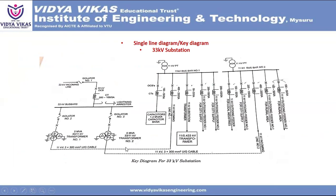From transformer 1 and transformer 2, they give another bus bar, number 1, the 11 kV bus bar. This is the 33 kV bus bar. This is the 11 kV bus bar. And then from the 11 kV bus bar, they give a capacitor bank to improve the power factor. And then this is the incoming circuit. And then from the 11 kV bus bar, they give an auxiliary transformer for the substation power supply. And then they use an 11 kV potential transformer.